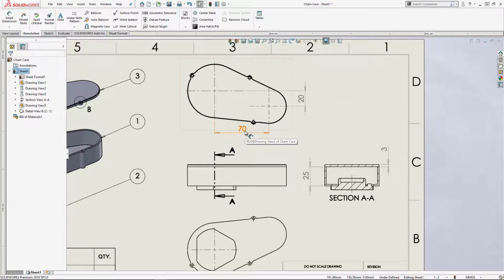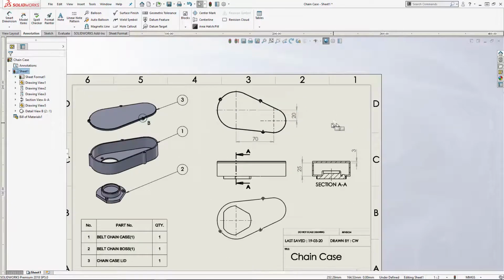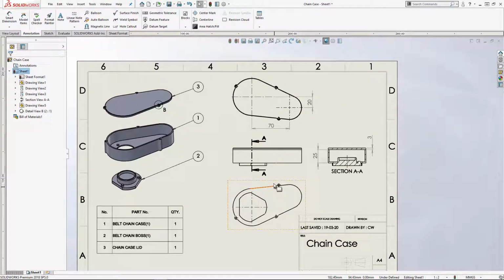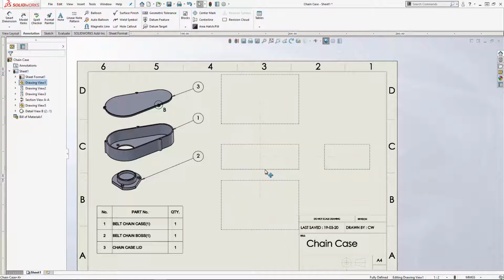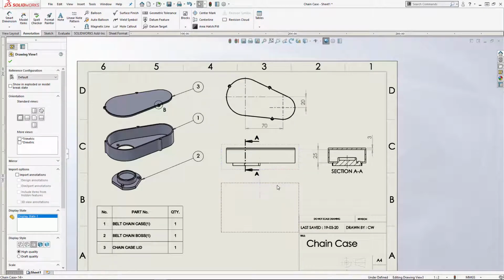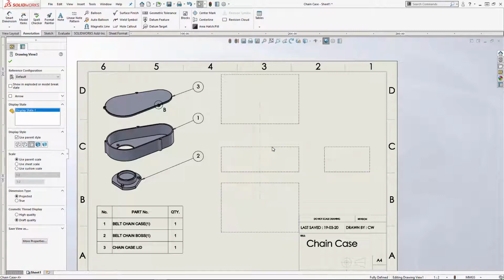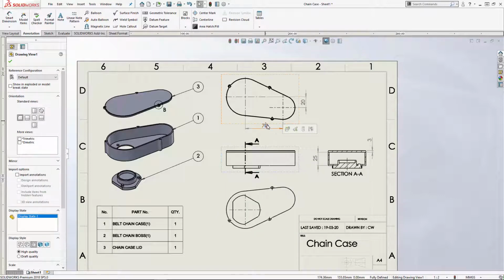Now in a lot of cases, in a lot of drawing departments, that distinction isn't required, and in actual fact it's quite damaging, because what ends up happening is you will distribute a drawing maybe to manufacturing staff, and they'll not understand why some of the dimensions are in grey and some of the dimensions are in black. So at the very least it will lead to an inquiry from them as to some sort of clarification as to what that means. And ultimately the answer to them is, as far as they're concerned, it doesn't mean anything. So it can be quite confusing.